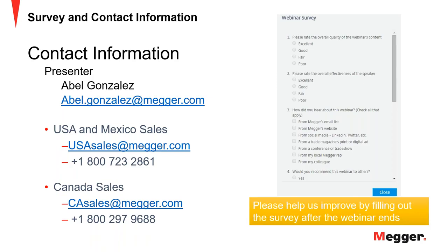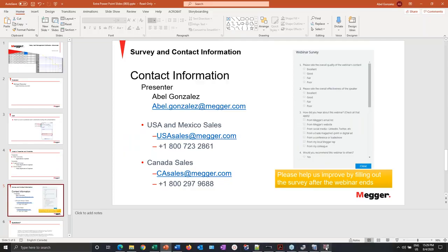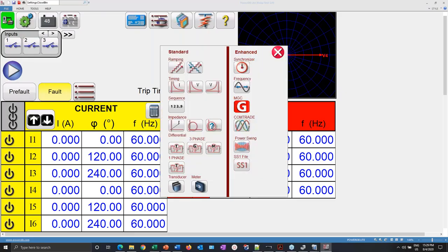The EZZ option provides more of a manual approach to perform basic impedance relay testing. The second method, the COF, is the click on to fault approach. This particular method, I would say, provides the most flexibility and complete test capability.